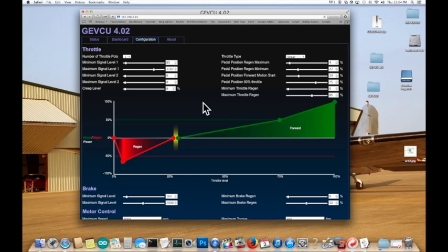We've updated the website in the Connect One, but the EEPROM chip where we had been writing variables, we've never changed that. And so we have the values that had been stored, and through various software trickery, we kind of make that fairly persistent because we don't want to lose those variables. But this is working against us on an upgrade.